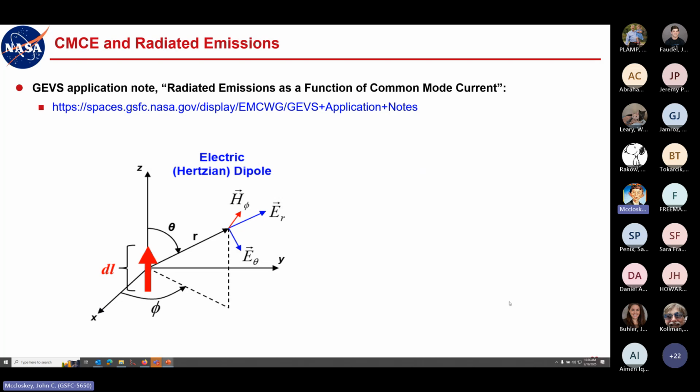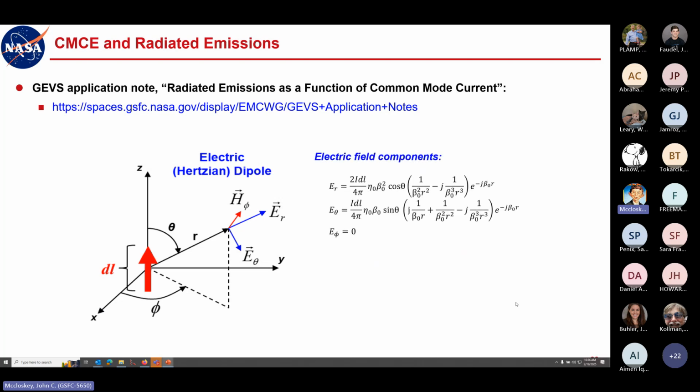This is that Hertzian dipole mess that I mentioned before. You can see that these electric field components are very complex expressions, and literally complex. They're j terms, they are imaginary components here. But all this is assuming a point source. So this is the sort of thing people will sometimes use to say, okay, we've measured this at 1 meter, what's the field going to be at 2 centimeters? So this is a very complex equation based on looking at this as a point source.